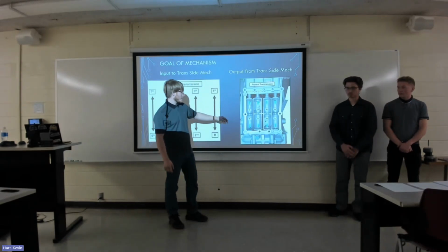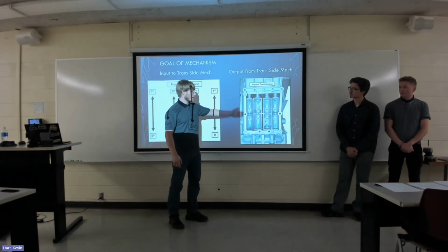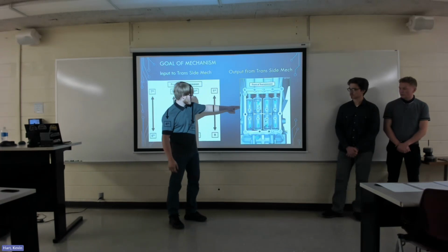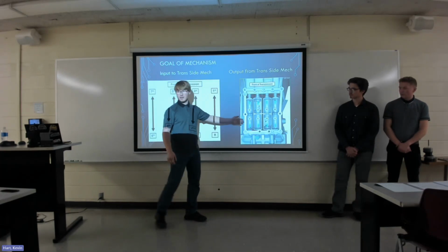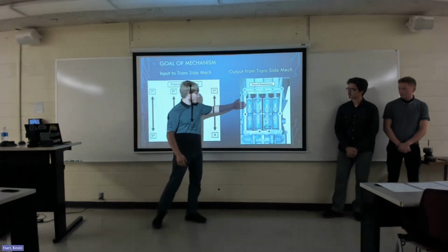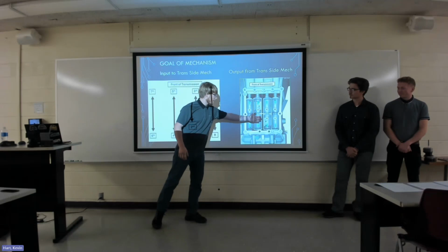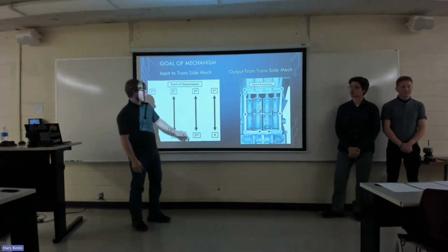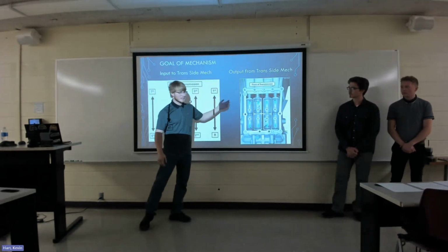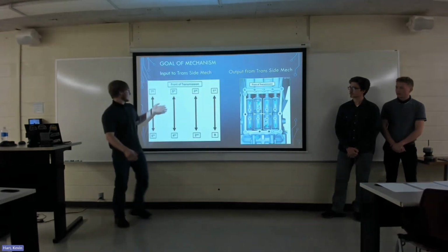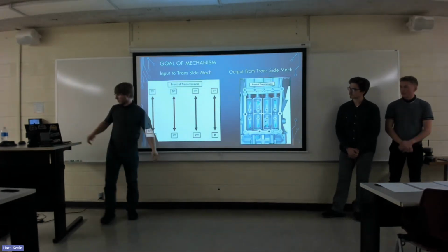Now you'll notice on the SMG layout, gears are not where you would expect them to be. So we have 2nd gear and 4th gear on one slider. We have 5th gear and 3rd gear on another slider. Additionally, you'll notice that 6 and 7 are on the same slider, but they're flipped in relation to this pattern, and same with first and reverse.